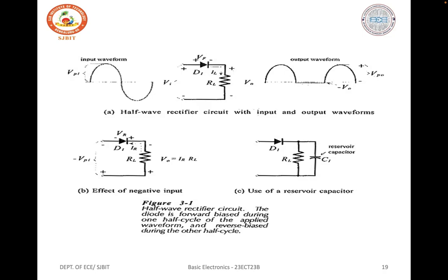Now the negative half wave rectifier. The effect of reversing the diode polarity in the circuit of the figure is that the negative half cycle of the AC input waveform is passed to the load resistor. Consequently, the peak output voltage and current are negative quantities. The figure shows a positive half wave rectifier circuit with the positive output terminal grounded. This is possible because the AC input to the rectifier circuit is normally derived from the secondary of a transformer.